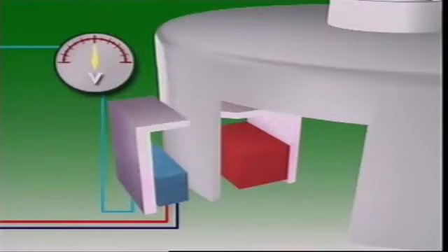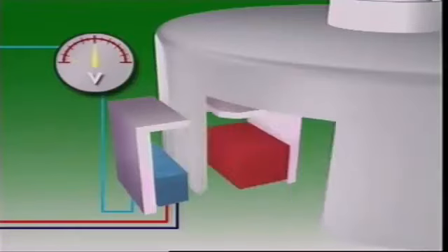When the interrupter ring rotates so that a blade is in line with the poles, the magnetic field is shielded and the signal voltage is not earthed. With continuous rotation, the blades repeatedly move in and out of the air gap, and the signal voltage will appear to turn on and off repeatedly. The control unit uses this on-off signal to detect engine RPM and to control ignition timing.